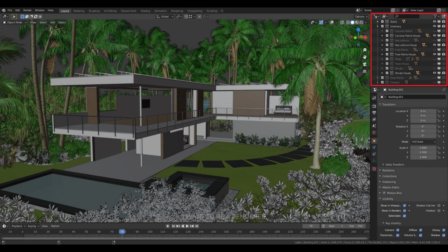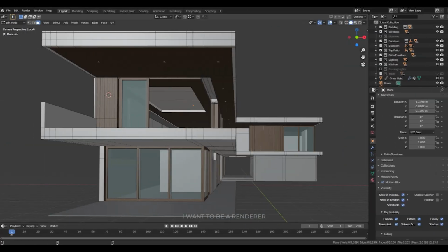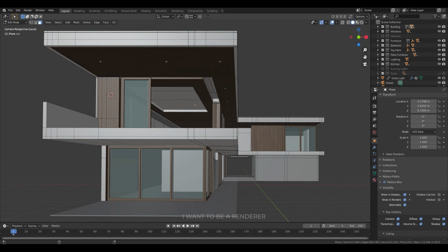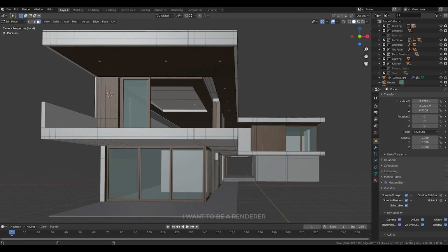When it comes to working with large projects, Blender does not like it. It would have to improve the RAM. To circumvent this, he divided the scene into smaller parts, a file for the house, another for the garden, and the largest, for the whole island. For complex projects, it can sometimes be a challenge to get started, and the best solution is to start with the simplest, in this case the house itself.